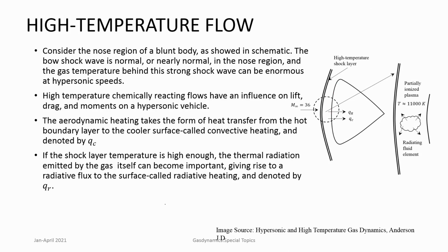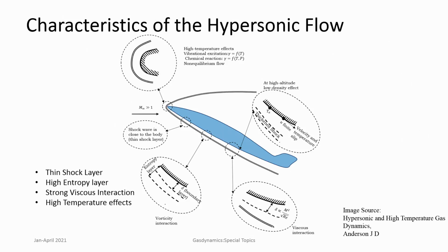So, this is the reason why the space shuttle is very rounded compared to any supersonic flights. Okay. So, high temperature effects become important in hypersonic flow. In all, if you consider a body in hypersonic flow, there are several aspects to it. One thing is shocks become very close to the body.